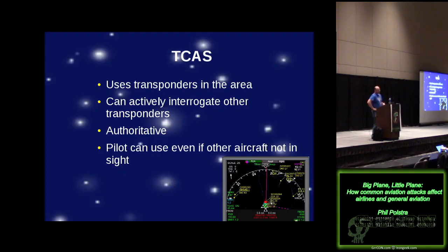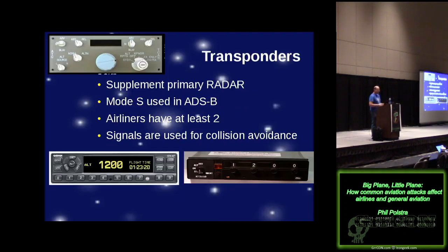But anyway, so what do the TCAS systems do? Here's the most important part about this. TCAS systems don't use ADS-B signals, right? You're not going to get an alert in your big airliner or your bizjet because I spoofed ADS-B signals. How hard is it to spoof ADS-B? Software-defined radio, ever heard of it? I mean, it's super, super easy. Like, I can make fake ADS-B signals all day long. It's probably not very ethical or legal, but I could do it. Right? The technology is very simple. But these guys don't use it.